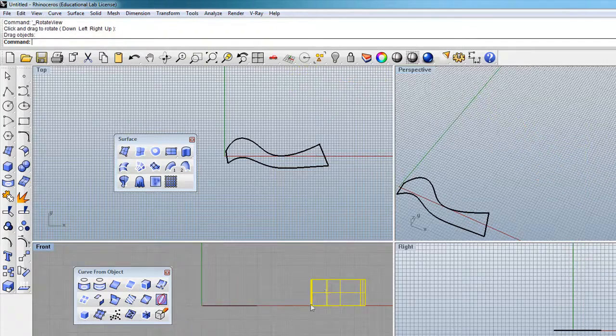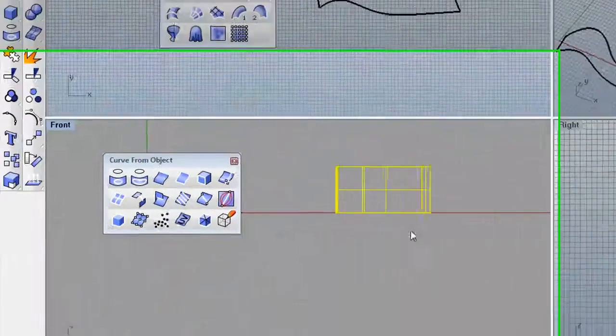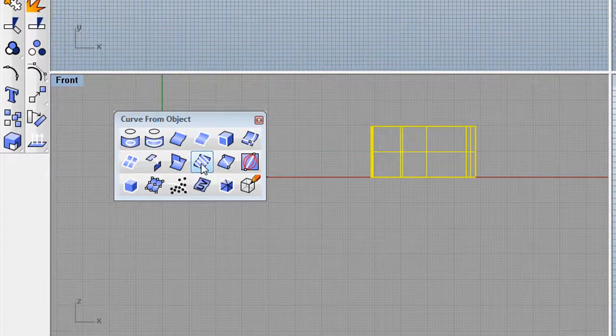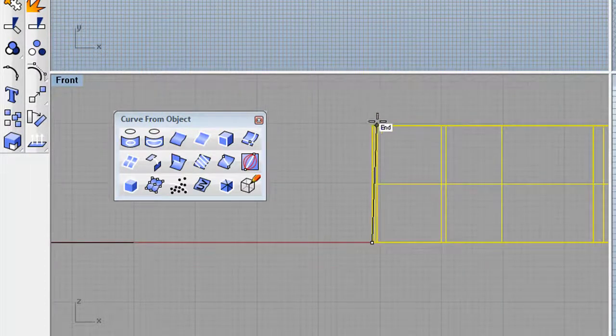Contour, you can understand it as a slicing tool. I will demonstrate to you. So I select the tool called contour, and I select the base point. For my case, I'm just going to use the bottom of the shape, and then I move up to the top, which I hope will give me a straight line. So that basically decides the direction.